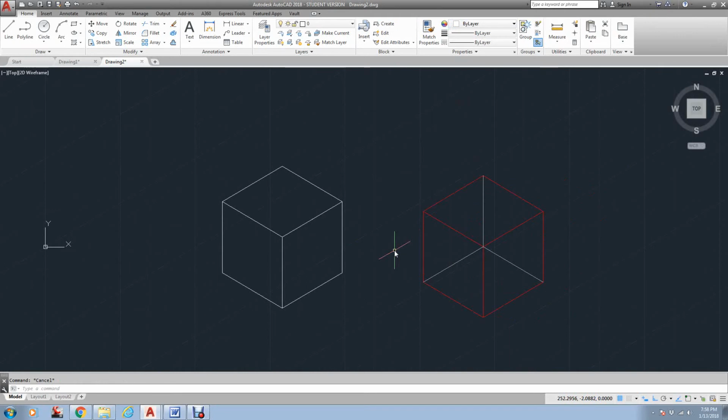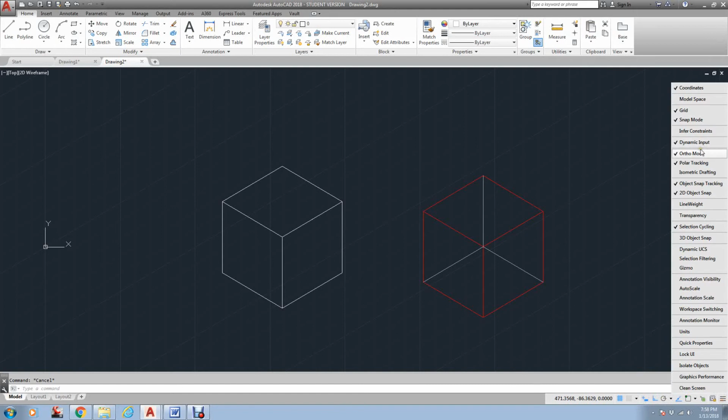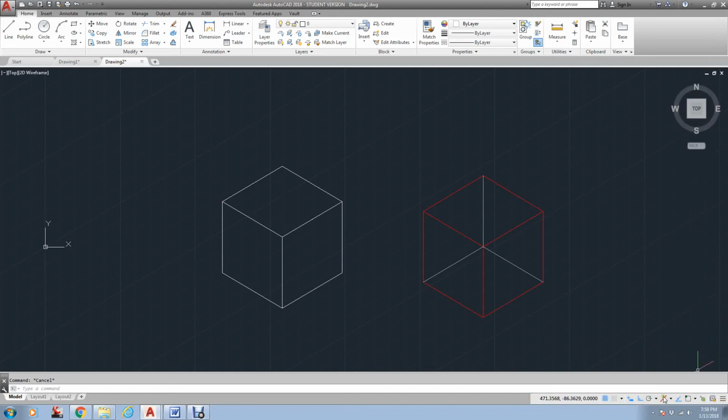So in dealing with an isometric, you're working at a 30-degree angle. Also on your newer versions of AutoCAD, over here under your customization, you can go to isometric drawing. That brings it down here, and it shows this little X. And here you can activate it. Here I'm back on rectangular. Here I'm back on isometric. I'm going to go back to rectangular just to show you.